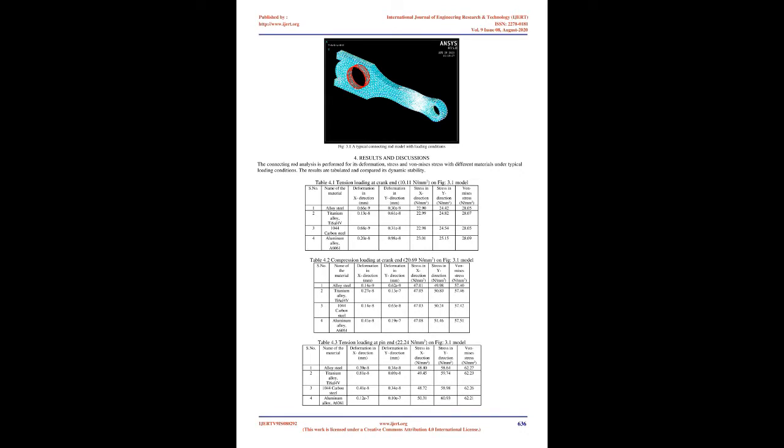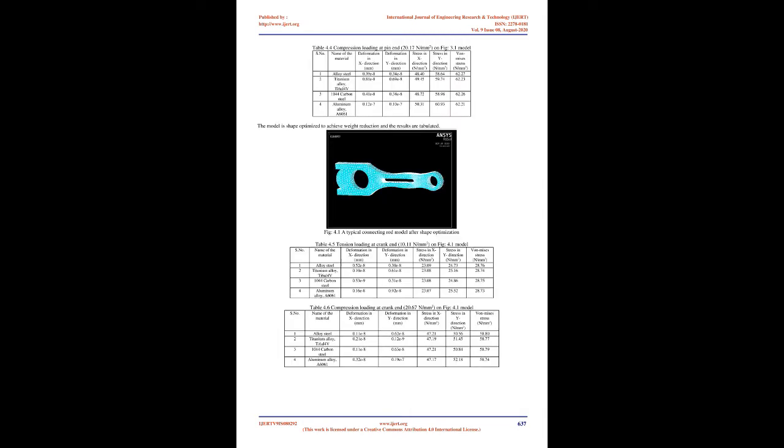Connecting rods are commonly made from cast aluminum alloys to withstand dynamic stresses from the combustion and piston movement. A typical focus is needed in evaluating the von Mises stress with different materials for comparison analysis. At present, 4 different materials are chosen for the comparison, and properties are given in Table 1.1.